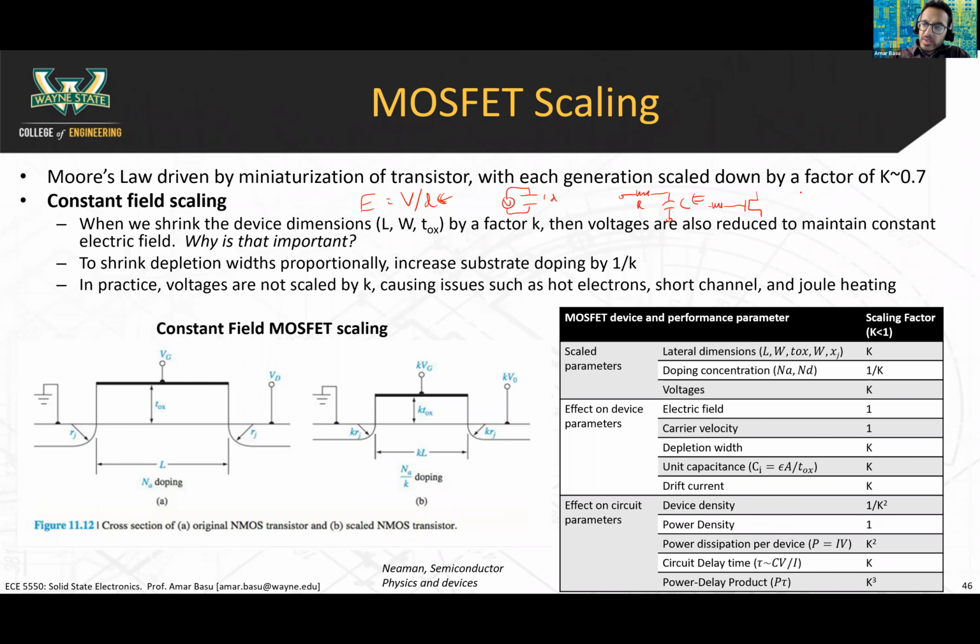That is because the time constant of a circuit is equal to RC, resistance times capacitance. The higher the capacitance is, the longer the time constant of your circuit is going to be, and the longer it takes to charge or discharge that capacitor. Charging means to increase the voltage on the capacitor, discharge means to decrease it.